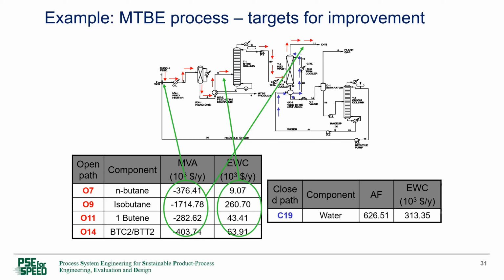After the distillation, the solvent goes to the absorber. And after the absorber, it goes back to the distillation, because in the absorber it removes methanol, and then goes to the distillation column to separate the methanol from the solvent, and the solvent goes back to the absorber. And then we can see that the amount of material going around is quite large.